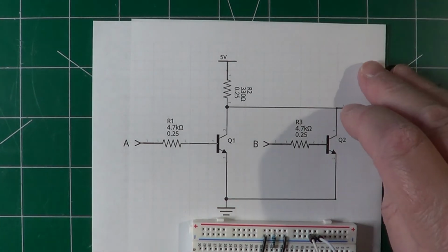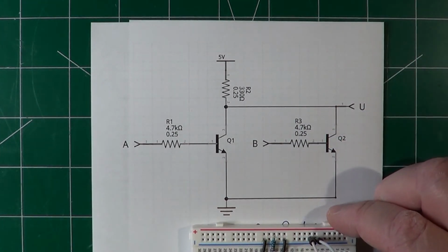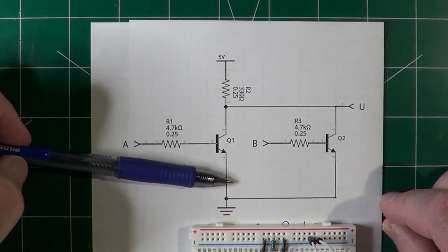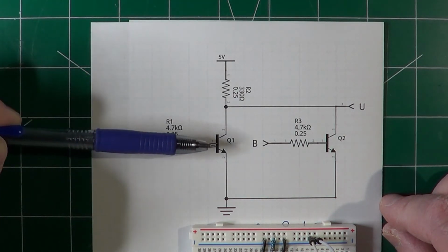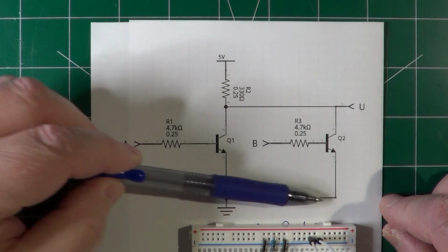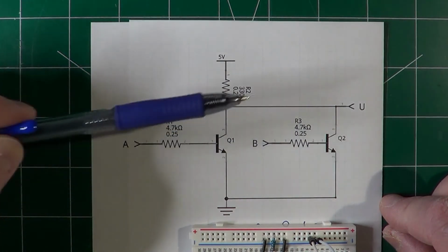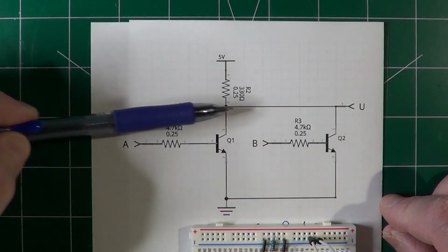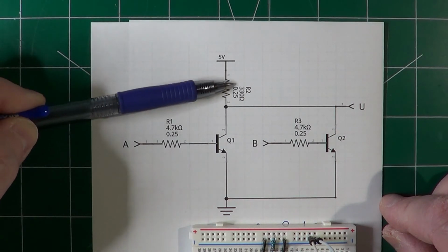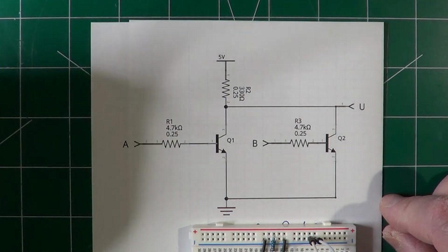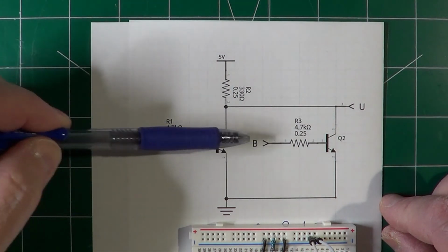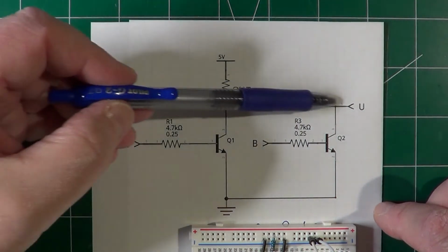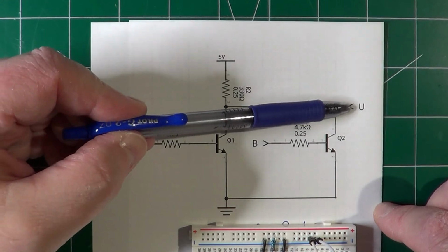And once again, here is our circuit printed on paper with actual component values. 2 transistors, the emitters are connected together and to the ground, the collectors are connected together and to the positive of the power supply through the now usual 330 ohm resistor. And finally 2 resistors on the 2 bases that constitute the 2 inputs of this logic gate. The output is taken on the collectors.